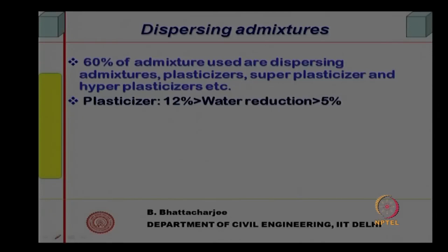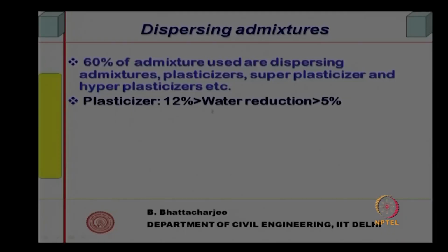As we said, that came pretty early, and this can reduce water. They plasticize the concrete. So, they essentially reduce the water demand in concrete. You can make it plastic with less water, that is the idea. If you add them into the concrete, they will make it more plastic, more flowable. Therefore, for the same plasticity you can reduce the water required.